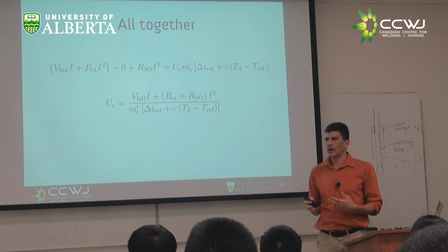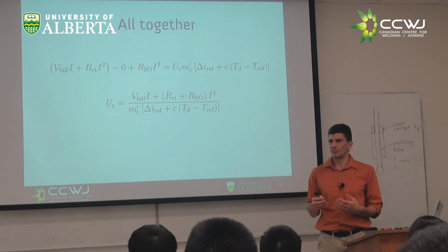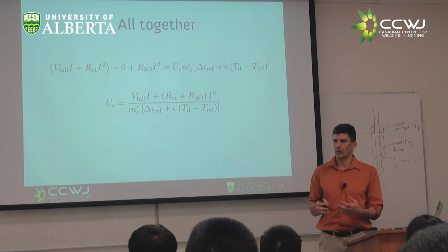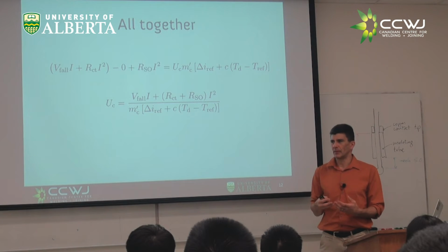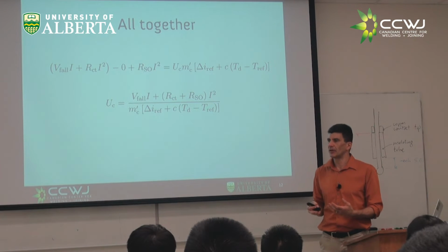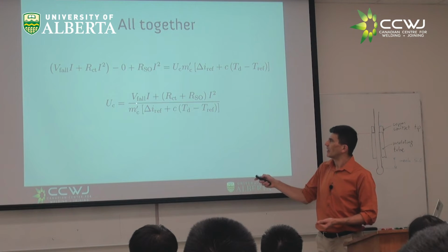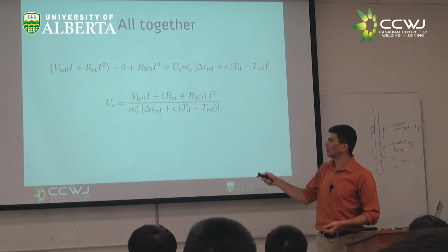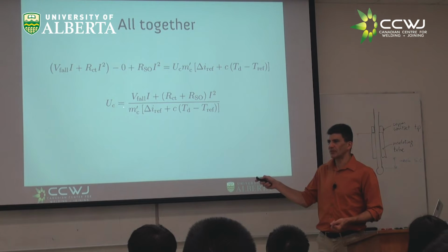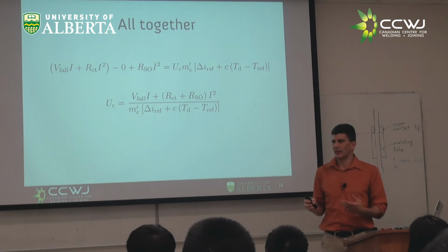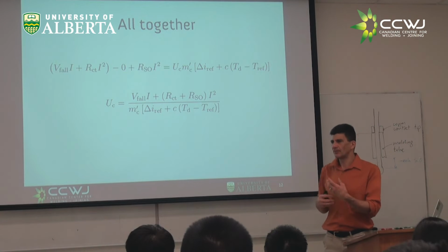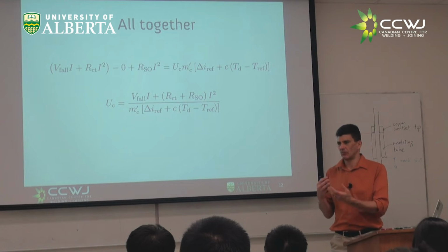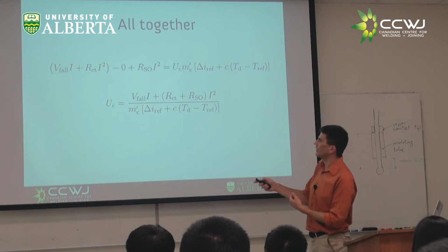If I flip the polarity and I go from electrode positive with a 4.8 volt anode fall to an electrode negative that becomes a non-thermionic cathode at 13.8 volts, I go from 4.8 to 13.8 here, the wire feed speed is going to increase. You knew that. Everybody knows that. They just don't know why, right? And if I do any type of variable polarity, I would get an average here.